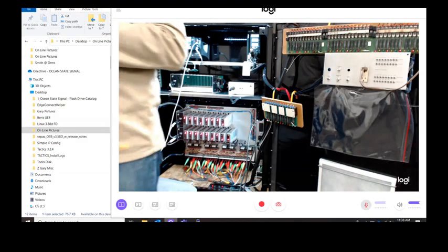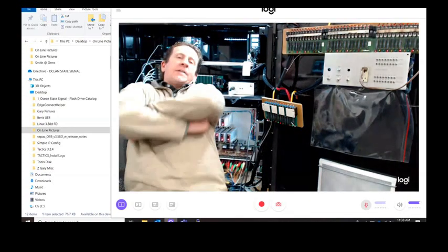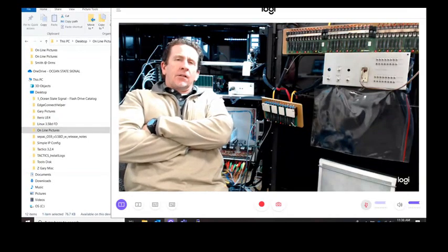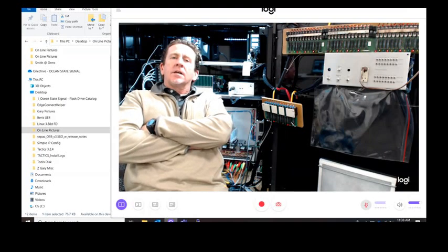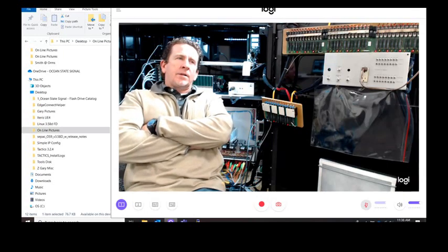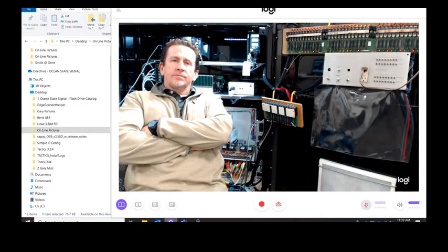Basically, all a yellow clearance fail is, if you go back to the programming where we did signal timing, we have red, yellow, and green timing. In the yellow timing, if any of you tried to change that 3.0 seconds to make it less, it probably didn't allow you to change it. The NEMA requirement is that the MMU or the conflict monitor has to see 2.7 seconds of yellow per phase. If it doesn't see it, then you'll get a yellow clearance fail.